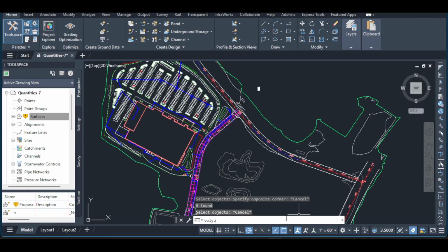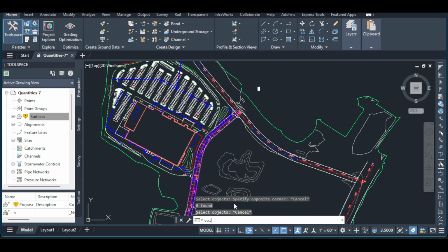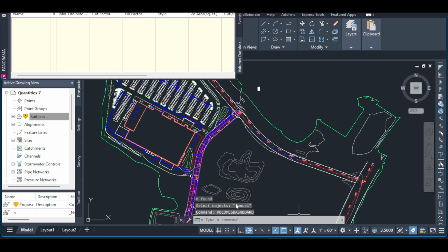Double check that you've selected the correct surfaces. Swapping them will flip cut and fill values, so this step matters. When you confirm, Civil 3D calculates a volume surface behind the scenes, triangulating the difference between the two. Now, review your results. You'll see cut, fill, and net volumes listed in your drawing's units, such as cubic meters